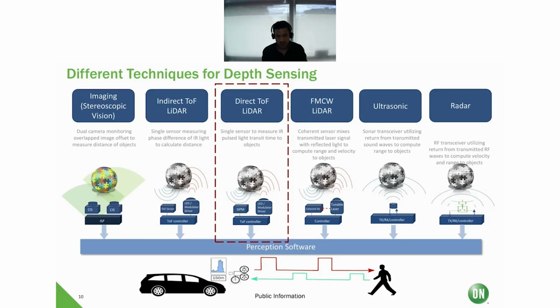The benefits that you have from using depth sensing with LiDAR versus other technologies like radar or ultrasonic are the depth resolution and the ranging distance. So for example, with a radar system, you are able to range to long distances, but you only get a certain few number of points across your scene, whereas with LiDAR, you can get a full view of the surroundings.